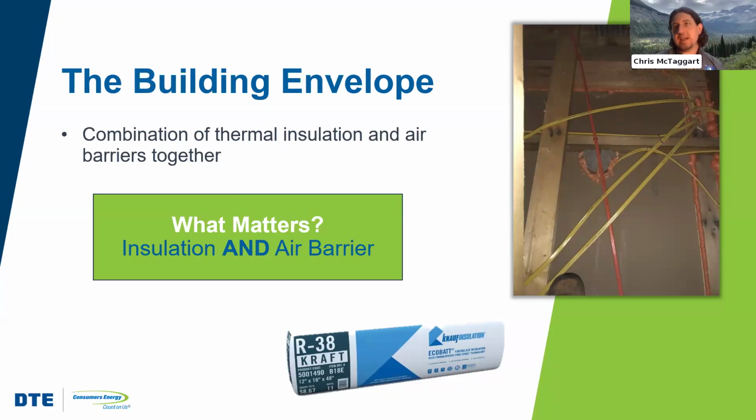Well, that's perfect because now we can go ahead and blow some insulation in on top of all that, or possibly bat it. I would probably blow it just because it's hard to split those bats around those framing members and those wires. So I'd probably just go ahead and blow in some fibrous insulation, whether it's blown fiberglass or blown cellulose. And we're going to be in good shape then, now that we have an air barrier, that sealed drywall plane, with our insulation on top of it. That's the combo that we're looking for in a building envelope.